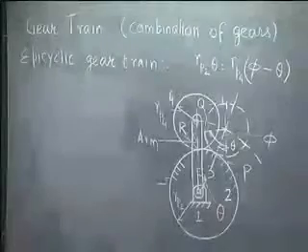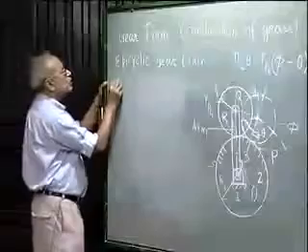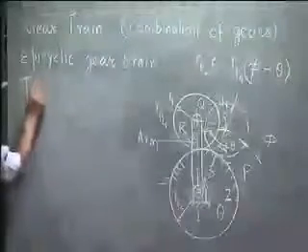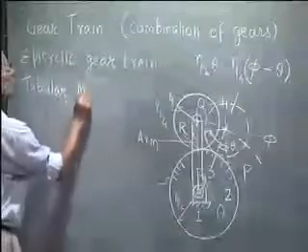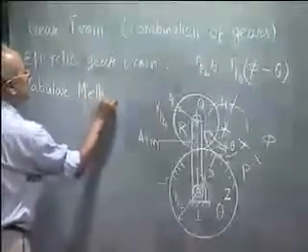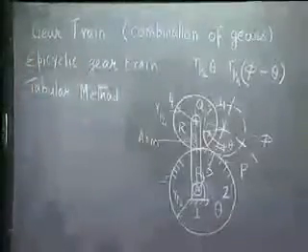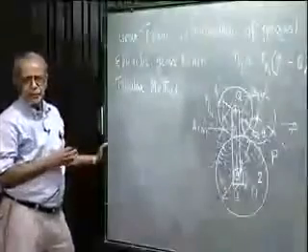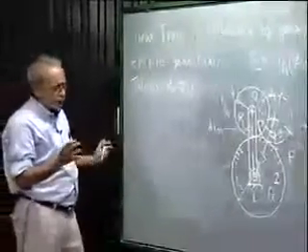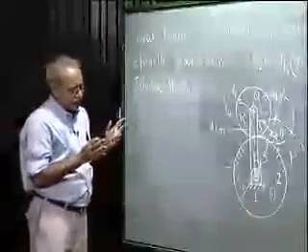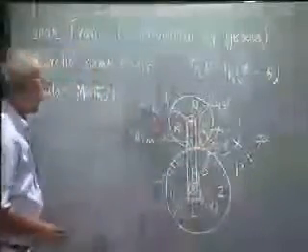So this we put in a somewhat mechanical tabular method. What we will do is, we first lock all the elements of a planetary gear train to the arm. All the elements are locked to the arm. That means the whole thing becomes one rigid body.